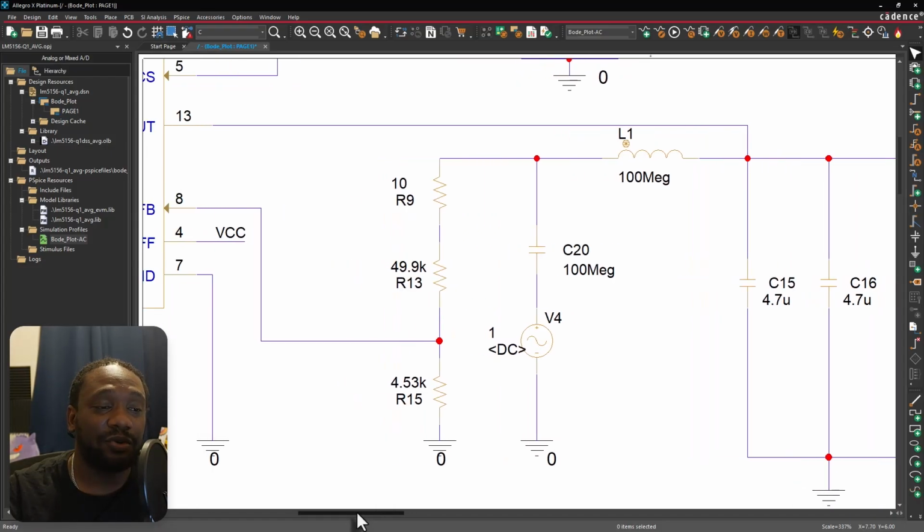And also, let's talk about phase. Phase is how much margin you have so that the controller doesn't flip the polarity of the error signal, of the signal that it's getting from the error. If it flips the polarity, then it's going to start adding more error to your problem. Okay, so we want to stay away from 180 degrees. I'll show that to you.